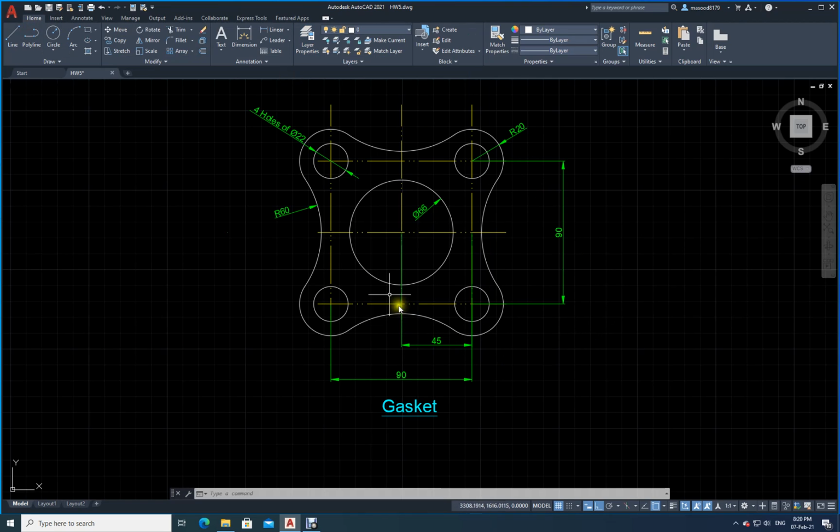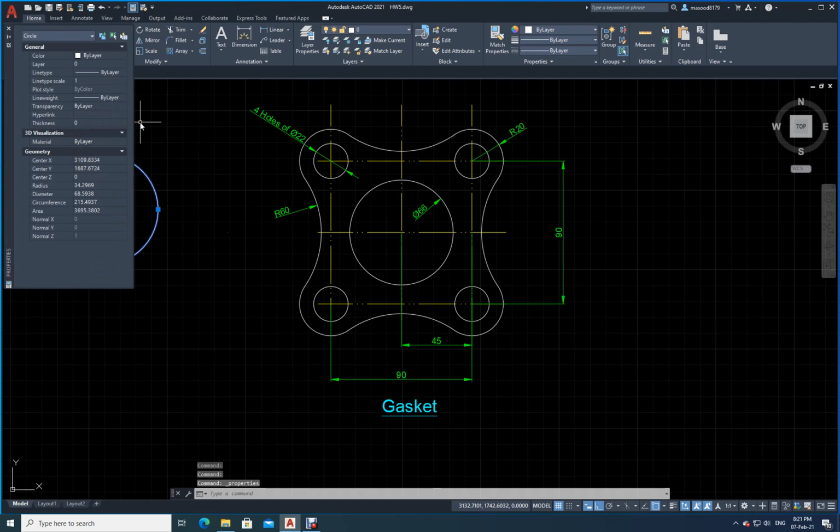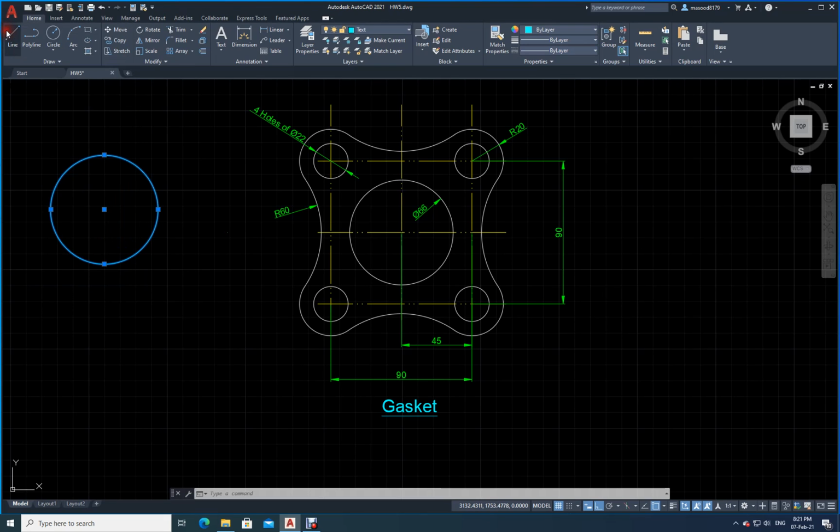Okay. So now whatever I draw, for example, let me draw a circle over here. You can see all the properties defined in that zero layer are applied to this particular circle. It is white in color. The layer is on. It is not frozen. It is open, means it is not locked. If by chance I shift this circle to another layer, I have got the layer properties over here, I can go and shift it here also. I right click and let me just shift it to the text layer. Now what happened?